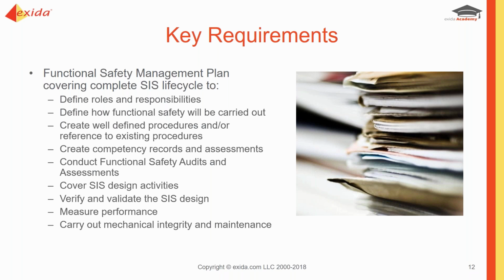And then we have to carry out mechanical integrity and maintenance. Remembering throughout the operation and maintenance phase of the life cycle, which can be 15 to 20 years, we have to make sure we follow the manufacturer's useful life recommendations. And we have to make sure that we have a plan in place to change out equipment as it comes to the end of useful life. So there needs to be mechanical integrity and maintenance.